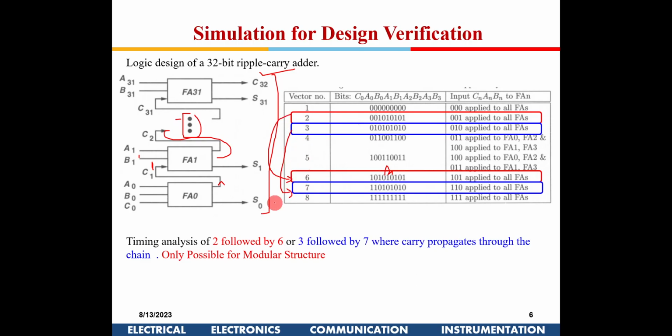So total 8 test vectors there and 2 test vectors here will give me this functionality check, and it will say, okay, this is functioning properly. We are not talking about fabrication at all. As of now, we are talking about the design verification or logic verification, that the desired output is available and it is meeting the timing constraints. So this is known as design verification. This needs to be done before we send the chip for fabrication. So these kinds of tests.